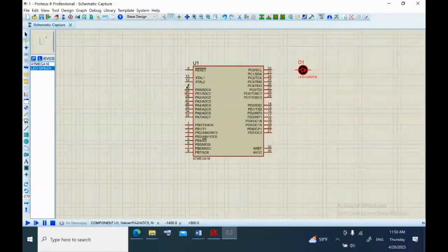For example, in our lectures, port A is placed on the right side, but in the simulation in Proteus, you see that the figure related to the ATmega16 is like this one. But anyway, the names of the ports and their tasks are the same. By using the datasheet, you can correspond the figure in the datasheet with the figure in the simulation.